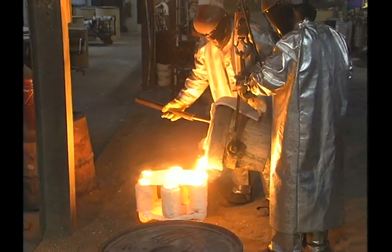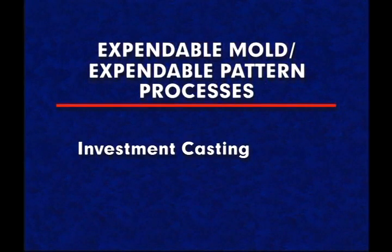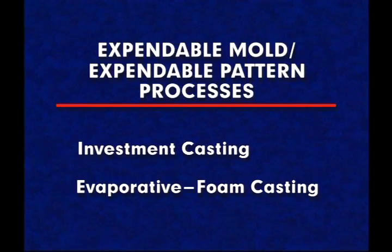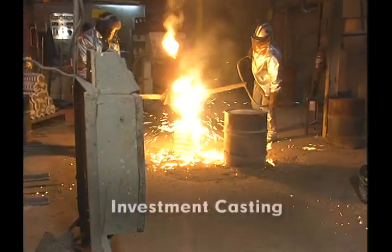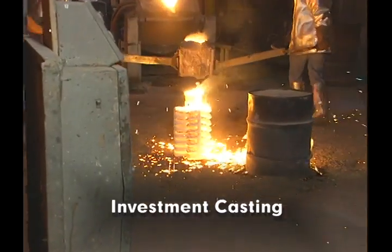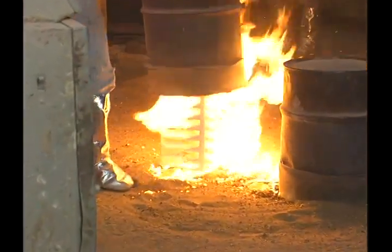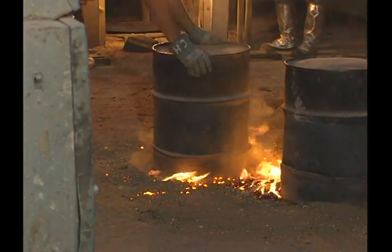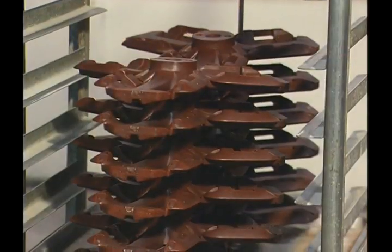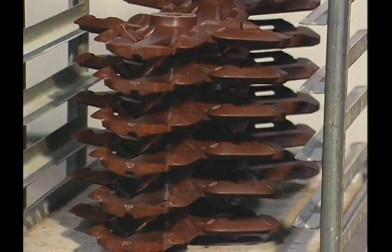Expendable mold, expendable pattern processes include investment casting and evaporative foam casting. Investment casting is a precision process using primarily ceramic shell molds. Investment casting is also known as the lost wax process because wax, a principal pattern material, is consumed during the mold-making process.